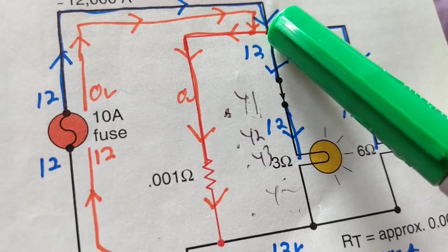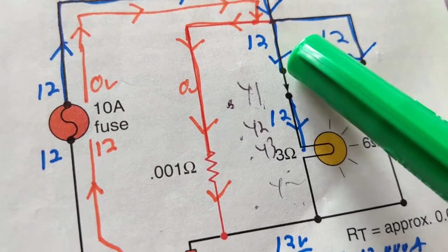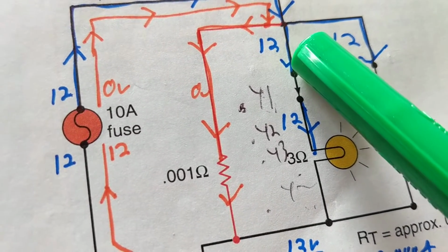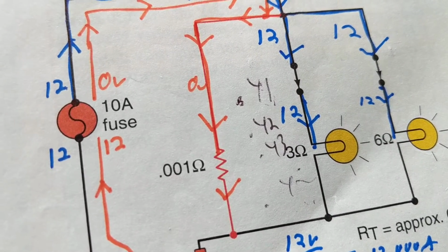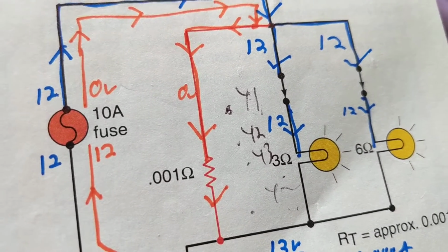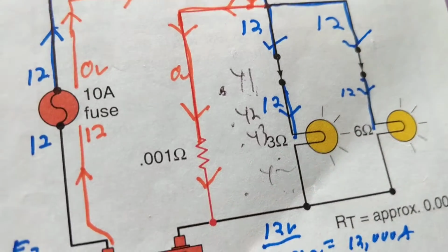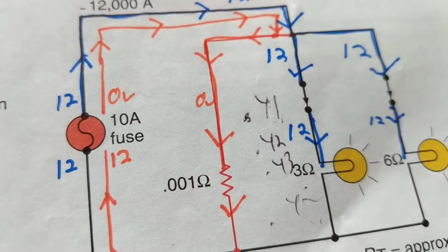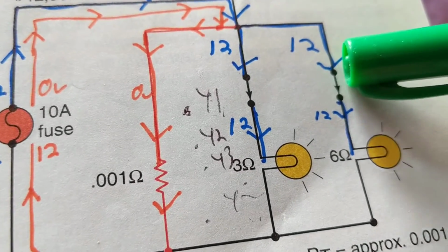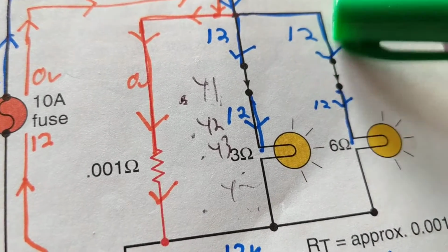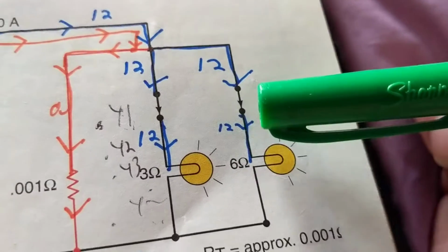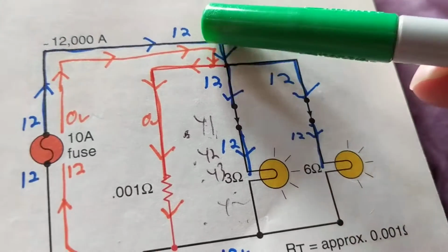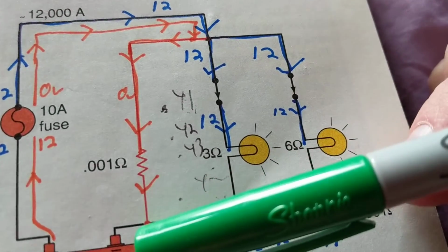Or alternator. If the alternator is running, engine is cranking, you're going to have 14 volts. Remember that. 14 volts. So therefore, the cigarette lighter or the adapter where you put in your phone to charge, if you go in there and measure 0 volts, what does that mean? That could be the fuse anywhere along that line. I lost my voltage. How about this one over here? Same thing as here, right? This is open now. How much should I measure over here? 0 volts. How much over here? 12 volts. Why? Because this is still connected through the fuse, through the battery.